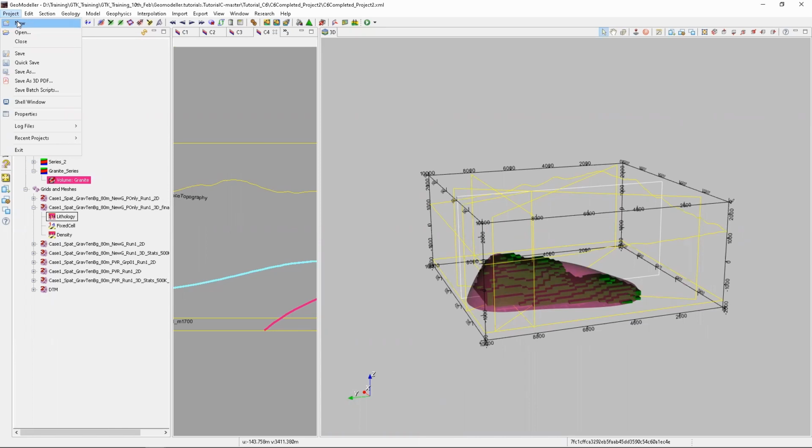No, that's fine. So you have the gradiometry survey over the same area that the previous data was. So it's good for comparison. Correct. So probably if your area has the FTG data, then you can do this operation to optimize your model. Yes, I agree that we don't find FTG data everywhere. It's a costly operation, but it's highly accurate when we use FTG data for the optimization.